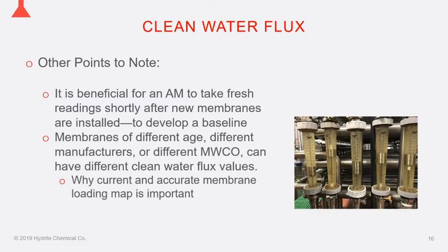You're probably wondering what's going on here. The reason for that, especially with an RO, is that as you concentrate material, your osmotic pressure goes way up. So it's not uncommon for the latter stages of an RO system to have nanomembranes, because they essentially will flux with lower pressures. And why is that important? Because it's much less energy consumption for the system to not have to get up to 600 psi to squeeze that last bit of water out.